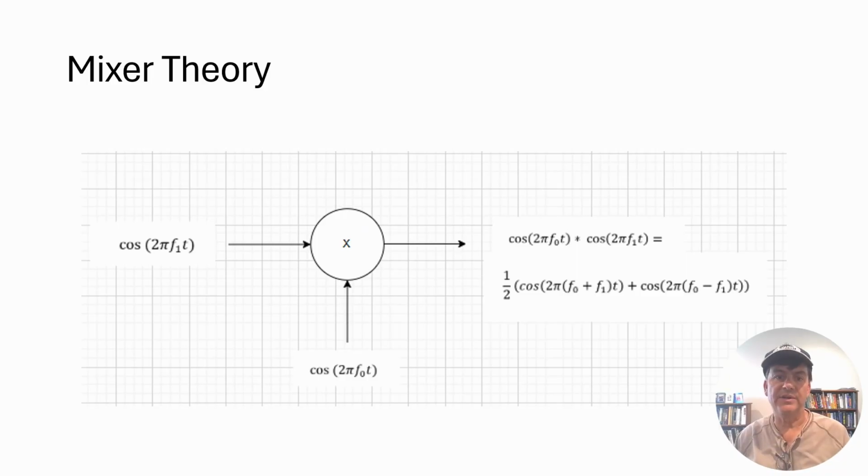A traditional mixer in IC design is the Gilbert cell mixer. Its purpose is to multiply an RF signal by a local oscillator in order to shift the signal's frequency. The mixer is composed of three main parts: a differential transconductance stage, which converts the RF input voltage into a current, an LO-driven switch quad, which reverses the polarity of that current, and load elements that generate the intermediate frequency output.